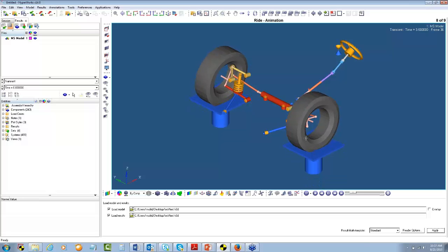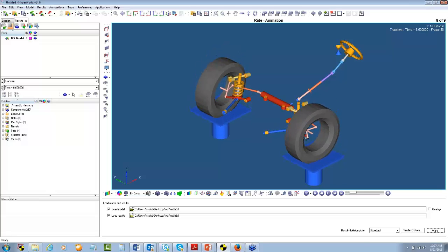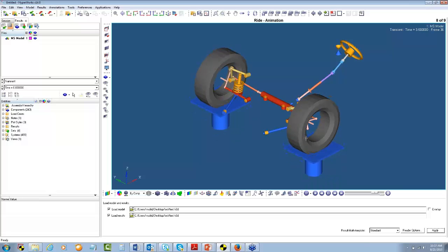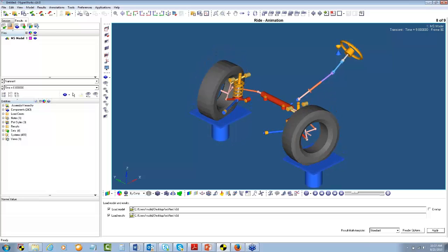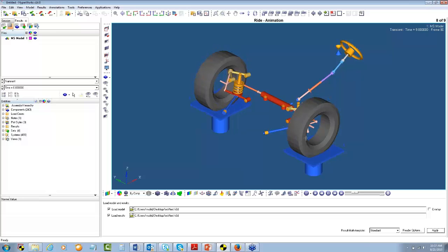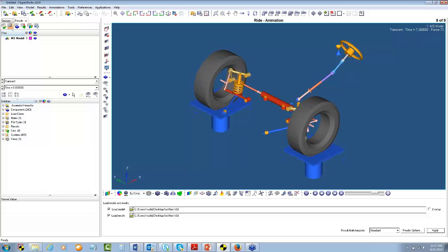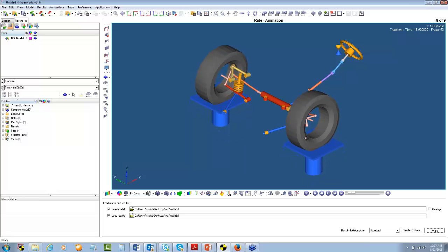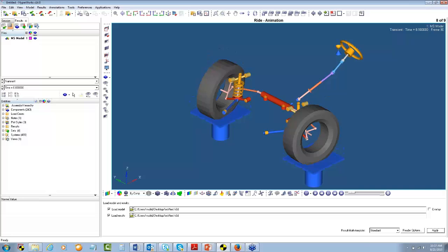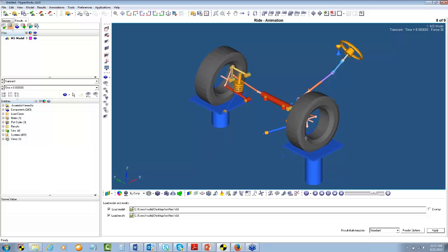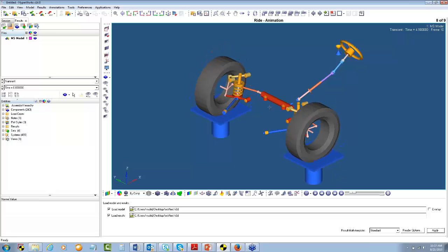Say your driver is driving on dirt terrain and you experience some kind of bump in the wheel. If that bump is equal on both sides, then of course that is going to cancel. However, if that is not so, then your vehicle is going to start turning, and the driver has to counter it, and that is just an additional burden. That is a bad design. So you need to take care of all these things, and that is where all these software tools come into the picture.